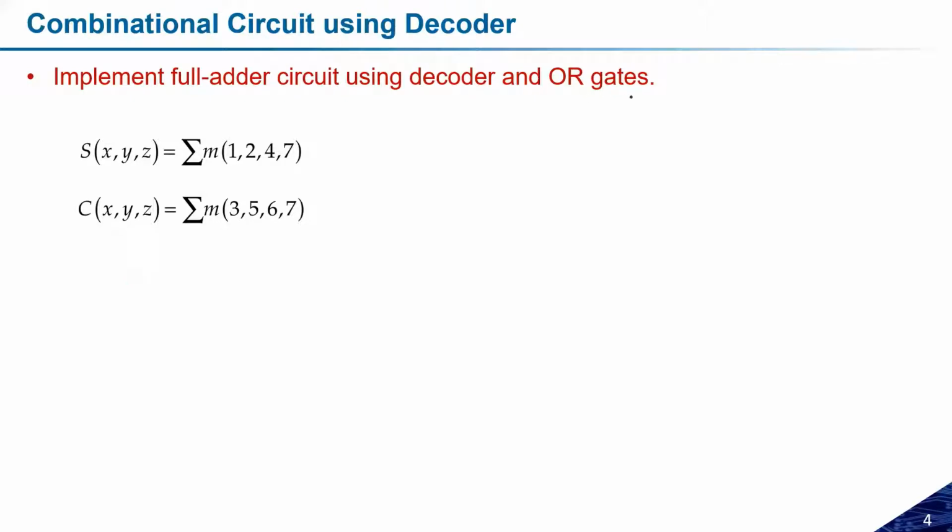I just told you, if we have an OR gate, it can be represented something like this. Here I need at least a 4 input OR gate, because I have the 4 minterms that I need to OR. So a 4 input OR gate is required. There are also some alternative symbols for the OR gate.